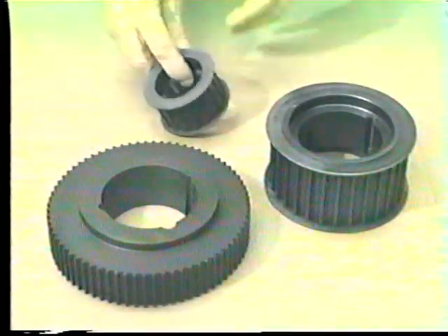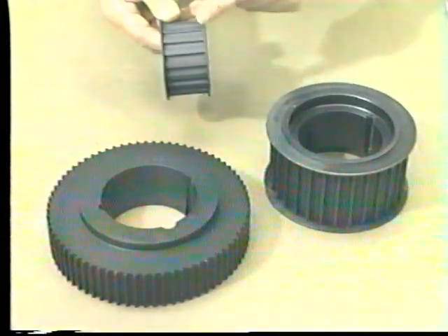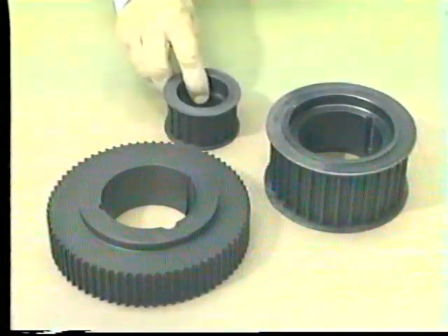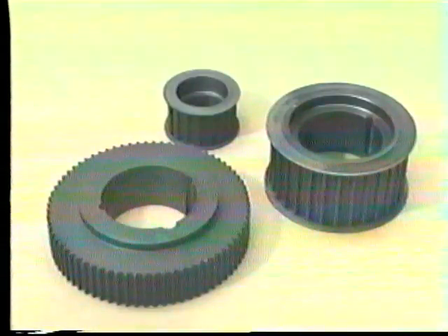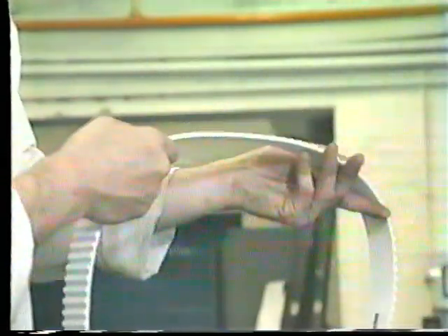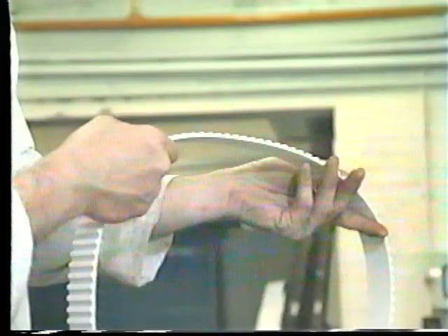Timing belts use sprockets that are very different from the pulleys needed for flat belts and V-belts. Timing belt sprockets are toothed, and they usually have flanges on both sides of the smaller sprockets to guide the belt. Because of the way they are manufactured, timing belts would run off the sprockets unless the flanges kept them in place. Timing belts do not generally need the precise tensioning required by V-belts. Usually a tight fit is all that's needed, because it's the teeth on the belt that actually transmit the power.